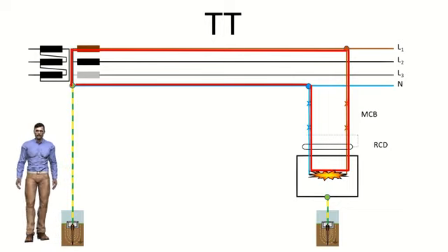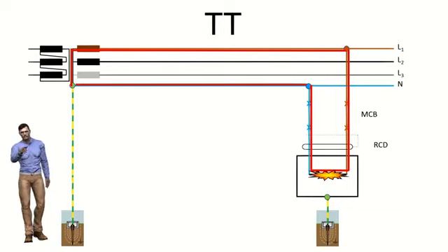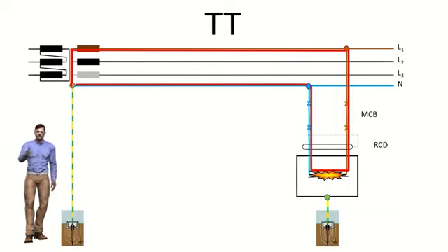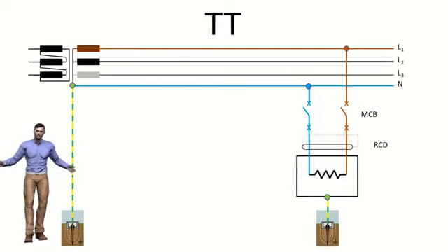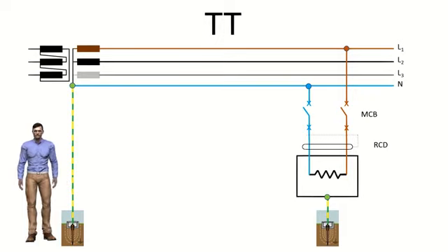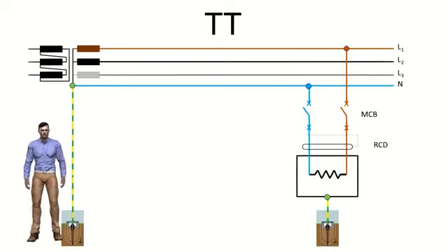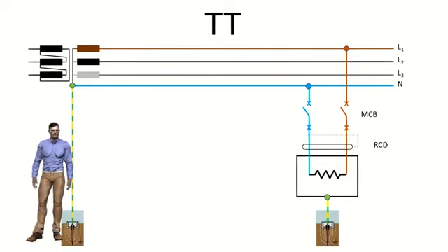Remember again Ohm's law, which tells us that the current is equal to the voltage divided by the resistance, so the smaller the resistance of the loop, the higher the current that appears. In this case we are talking about short-circuit currents. This high current must be detected and broken by the protection against overcurrents and short circuits, which falls on the fuses and circuit breaker protections, although as I have mentioned we can have combined protection systems.